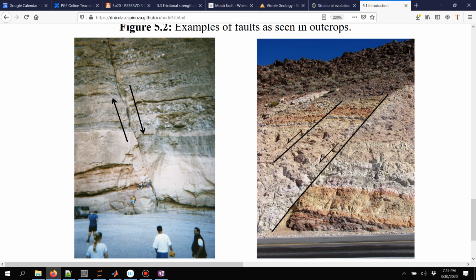It may not be necessarily the same. The stress regime may have changed, may have gone from normal faulting to reverse or to strike slip, or it may be still normal faulting, but it may have an orientation of the minimum horizontal stress different, let's say not in east-west direction, but now in north-south direction.